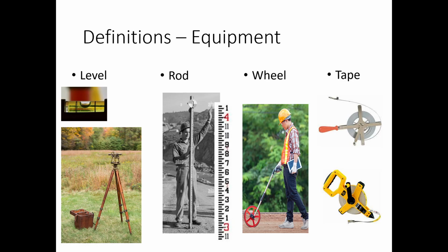So getting more into surveying terms, and this is probably older, but these are the generic terms, but they stand for a lot of different things. So just the idea of a level, obviously we're more familiar with something being level, represented by a bubble, like that. But in surveying, generally, a lot of times we refer to this entire instrument, so we have our tripod and then our ranging instrument, and this whole thing kind of gets thought of as a level. And the idea behind that is once you set this up, you generally adjust it until it is actually level. And so with the instrument, you have a singular plane or line of sight over which you survey, and we'll get into that type of surveying, but that's kind of where that idea comes from.